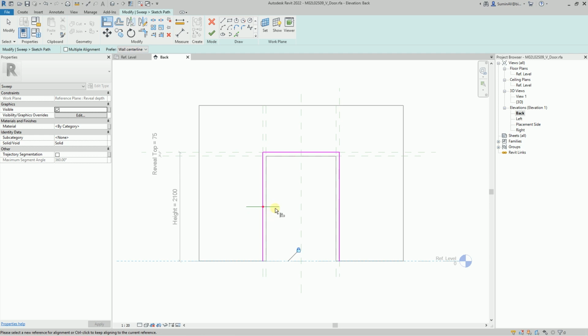It's important to place the path so that we can then choose a comfortable view to form the profile. In this case, it will be a floor plan, because its plane is parallel to this profile construction plane. For example, we cannot build a profile on the elevation views, in this case, since any elevation is perpendicular to this plane, and the profile is a 2D sketch, and, under these conditions, it will be projected into a line.